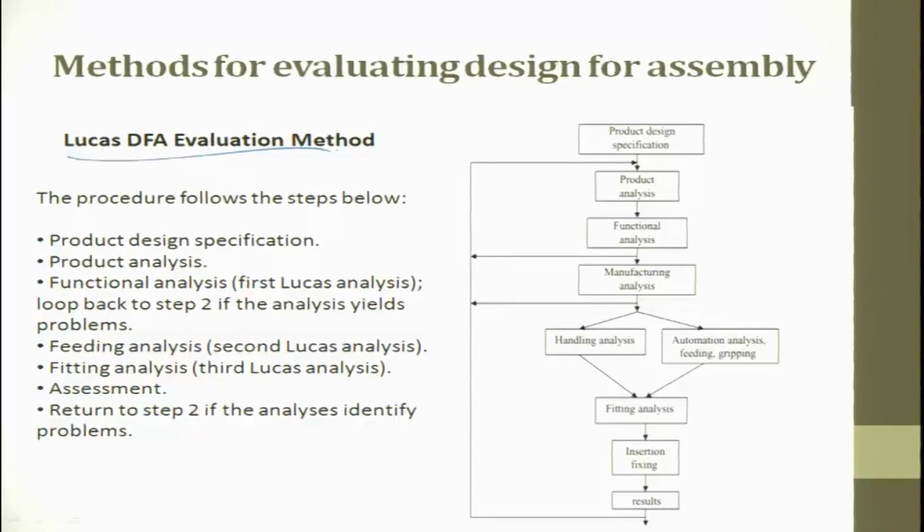The next method is the Lucas DFA evaluation method. So, here the product design specification, product analysis, functional analysis. Functional analysis, this is the first time people started talking about functional analysis, then they talked about manufacturing analysis. The functional analysis loops back to step 2 if the analysis yields a problem, and then what you do, you reiterate and then come back. Then you get into manufacturing analysis.